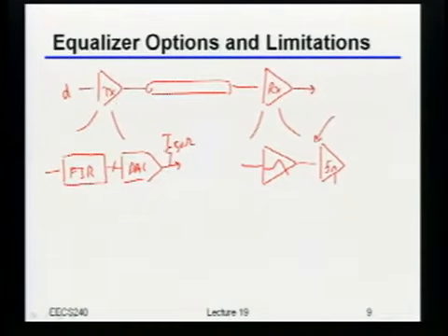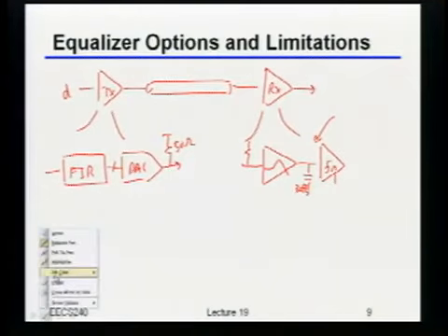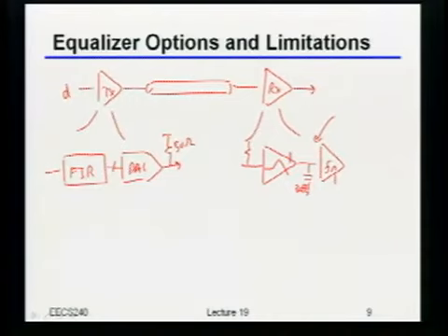At the receiver, yes, I still need my 50 ohm termination at the input. But if I've got something like 30 femtofarads of capacitance, for example, like I told you in the project, coming from the comparator, the impedance of that capacitor, even at 5 gigahertz, is pretty high, right? A lot higher than 50 ohms. That means it costs me a lot less power to get the same voltage swing. So because of that, I claim that even once you're doing this equalizer, you tend to want to do it on the receive side, simply because that results in lower power.